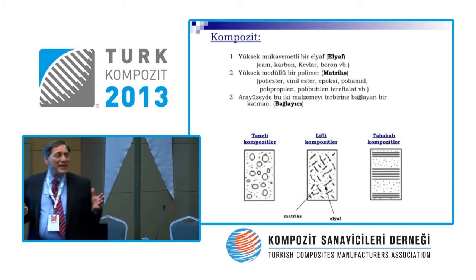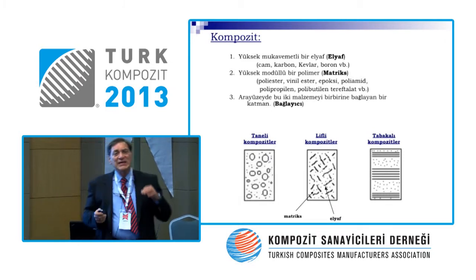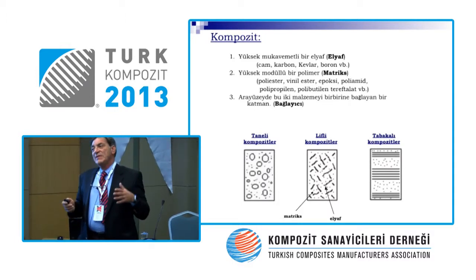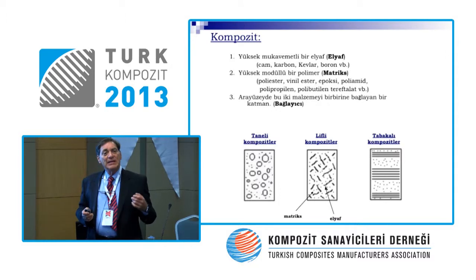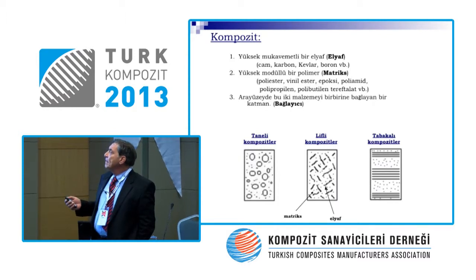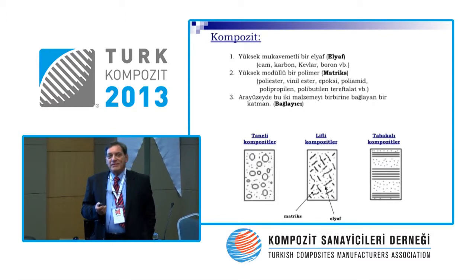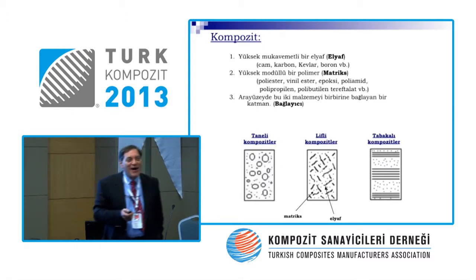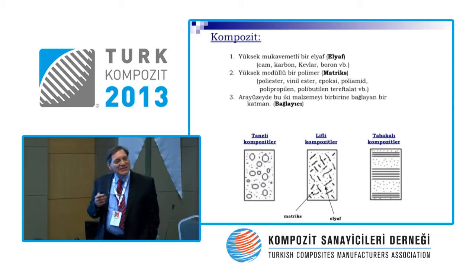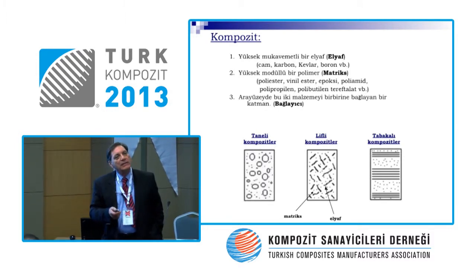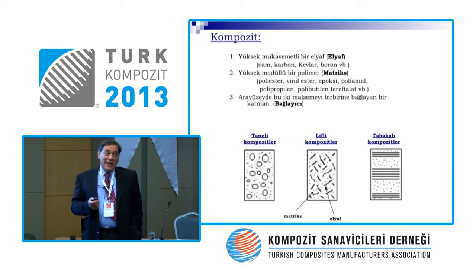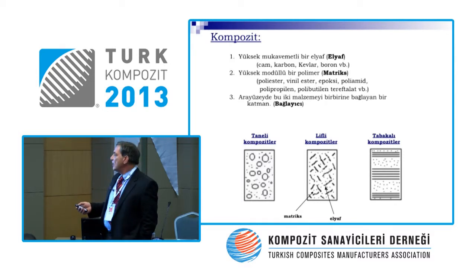But they are actually structures that are not alike to each other. Some are organic non-polar polymer, and on the other hand there is inorganic polar fiber, if we are talking about carbon and glass. So there is an interface here that connects each other, and that interface is actually what makes up this composite, of course. If the stress transfer in a material cannot reach the fiber, and the matrix volume is actually 150 times more than the fiber, if we cannot put any load on the fiber, then your composite doesn't work at all.